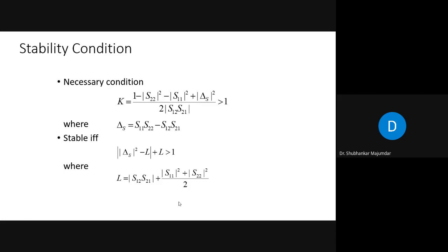Then for that matching circuit also some stability circuits are required, and for output matching circuits also some stability circuits are required. Then we require a gate biasing and a drain biasing. Both biasings should be different, because the gate driving capabilities are different. Like if we are using an enhancement mode, the gate is driven at 1 volt or 2 volt, whereas the drain is biased by 28 volt or 48 volt, like that. So both the circuits are different.